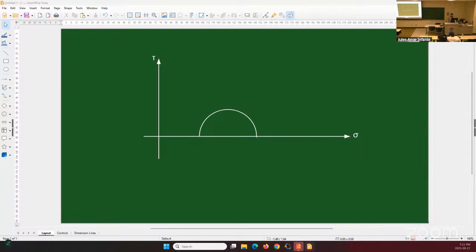So the principal stresses are where? Where would I find my principal stress? So yes, I would have here, sorry, sigma one. And technically I could have sigma two and then another, there are three circles we can draw, sigma one, sigma two, sigma three. But typically sigma two and sigma three are set equal in an isotropic kind of environment. So in most cases, we'll assume that we deal with sigma one and sigma three.